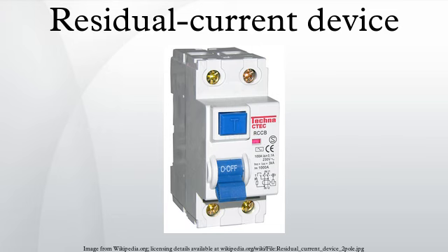Other arrangements, such as the use of RCBOs, may be employed to meet the regulations. The new requirements for RCDs do not affect most existing installations unless they are rewired, the distribution board is changed, a new circuit is installed, or alterations are made such as additional socket outlets or new cables buried in walls.